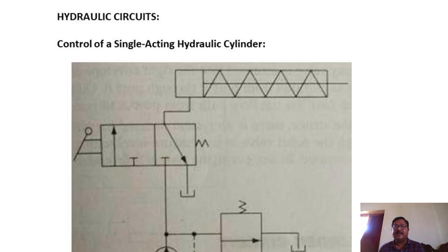Counterbalance, as we know, in some of the cranes and some of the lifting equipment we are all seeing day by day in our life, a quantity of weight is lifted from one side. On the other side, the counterbalancing is needed, because we don't know how much weight is lifted on that side. It is only designed for different tonnages, different tons of capacity. But if you apply the counterbalancing weight to the other hand, then the equipment weight will increase. Otherwise, what they are doing is, the hydraulic counterbalancing valve application is applied in hydraulic power lifting equipment.